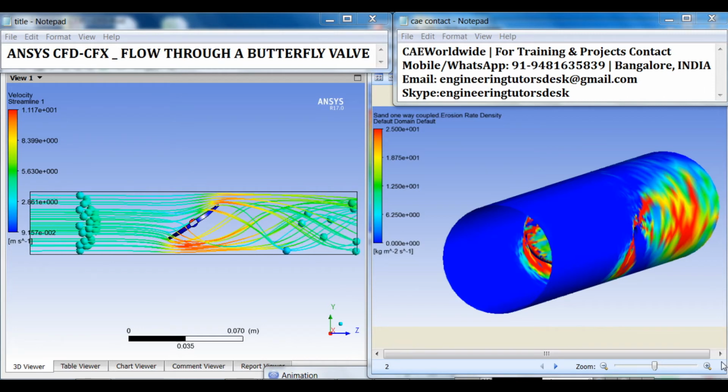As fluid enters any pipe or channel, boundary layers keep on growing till they meet, after some distance downstream from the entrance region. After this distance, the velocity profile doesn't change, and the flow is said to be fully developed. Here we consider fully developed velocity profiles from an accuracy point of view.